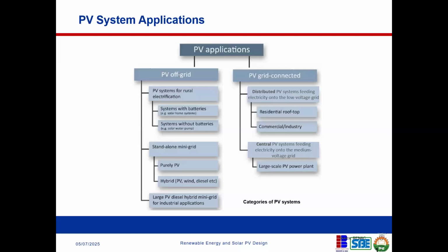Imagine that maybe your demand is, for example, 500 kilowatts. Okay, that's your demand. And out of that 500, only 200 is coming from the solar system, meaning that 300 is coming from the grid. What happens if the grid fails? So what will actually happen is that once the grid fails, the solar system will shut down. Okay, but some of these are designed in such a way that once the grid fails, the solar system controller, not the control panel, will automatically start your generator and then connect you back to supply.